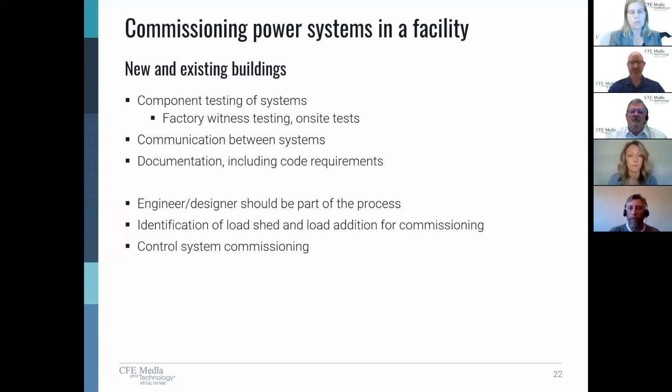Within commissioning, all the way down to the black site test, documentation is critically important. You want to know exactly what numbers you're getting. It might be voltage. So when the generators come up, do you have voltage sag anywhere? Are they over voltage? That sort of thing. Sometimes you're seeing readings that don't seem to really stand out. They will stand out later on down the line in interaction with different equipment, and having that data to be able to go back to is very important.